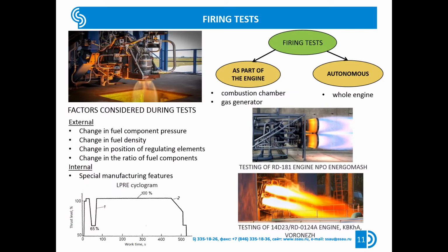The operation process of a chemical fuel-powered LPRE involves the combustion or decomposition of fuel, which produces large amounts of heat. The resulting thermal and dynamic loads have a major impact on the engine's working process and the performance of its components. All this has to be simulated in a test. There is only one way to do this, by running the engine. At the same time, the use of high-performance and often aggressive and toxic components in liquid rocket engines makes the testing process dangerous and expensive.